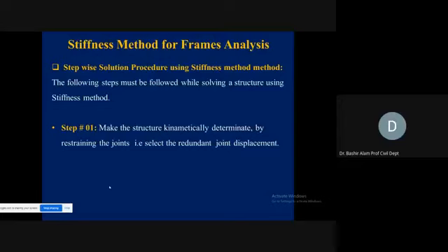We declare the Ds unknown, we fix their direction and location, and then corresponding to those, we look for the externally applied actions and include them in the AD matrix. So the AD matrix is constructed in the first step.